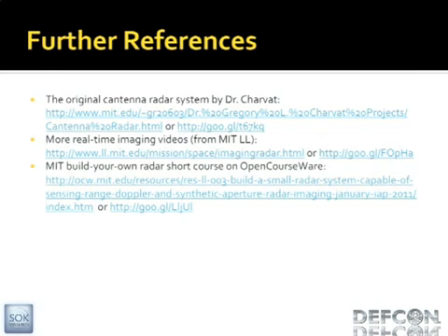So you could go up to 5 gigahertz. It would be a little harder to find parts. Basically, as you go up in frequency, the parts just get a little more expensive, or as you get even higher, they can get a lot more expensive. But the big thing you want in a system like this is wide bandwidth, because the bandwidth is what's giving you that spatial resolution and the time resolution. Anyone else?